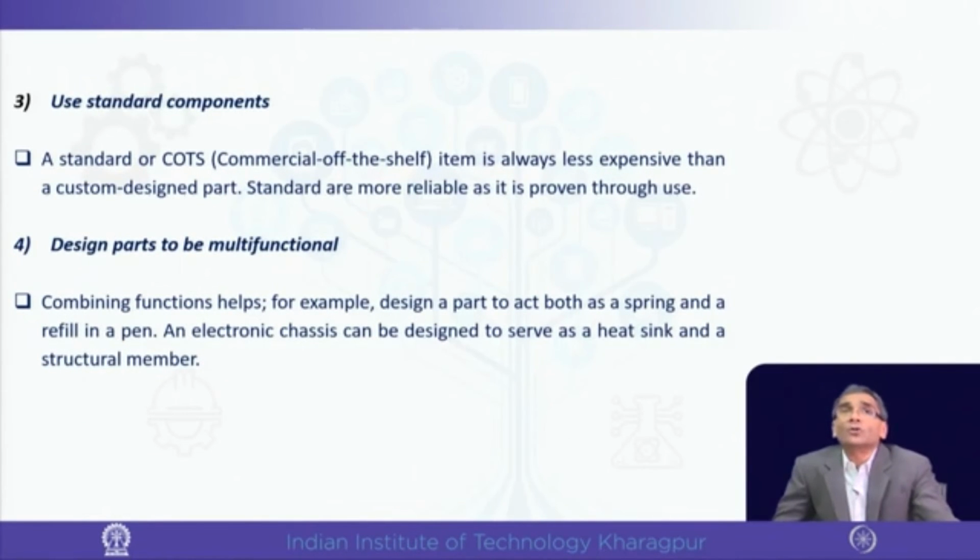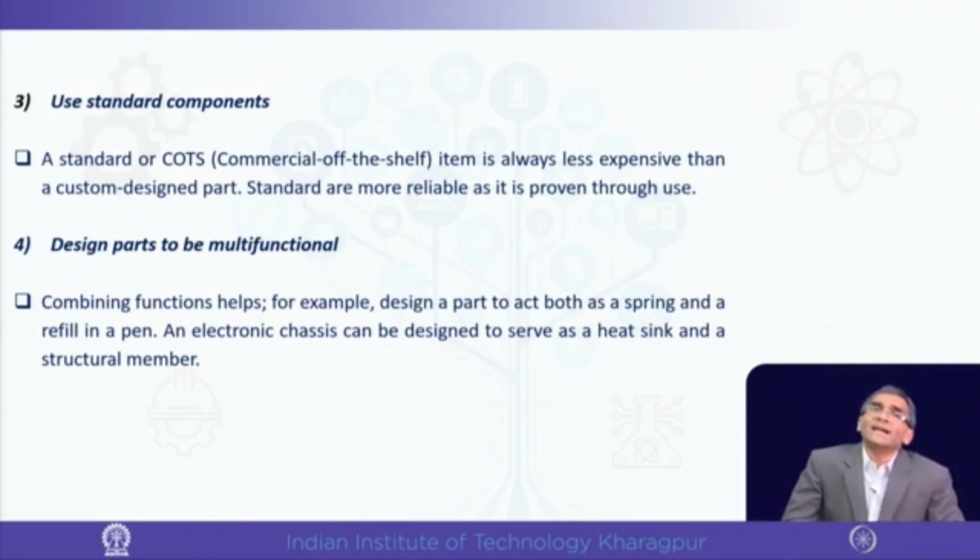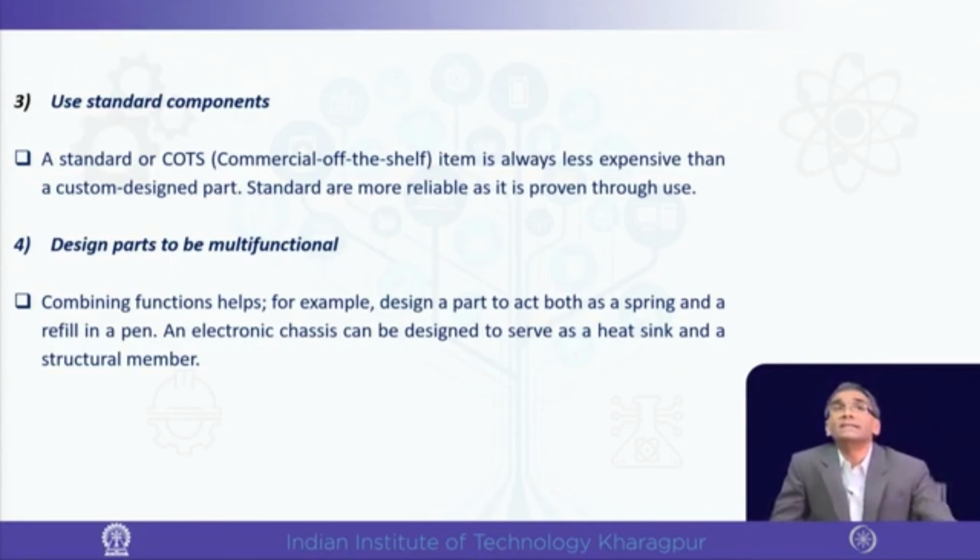Use standard components or COTS, called commercial off the shelf, say fasteners, nuts, bolts, bearings, certain switches and all those kinds of things which are standard and available in the market. There is no point designing them. If they are used in that product, that is better, for two reasons. One is that since those are being mass produced by some company, their cost will be less, and two, because of the ongoing manufacturing for several years, their designs are proven and established.